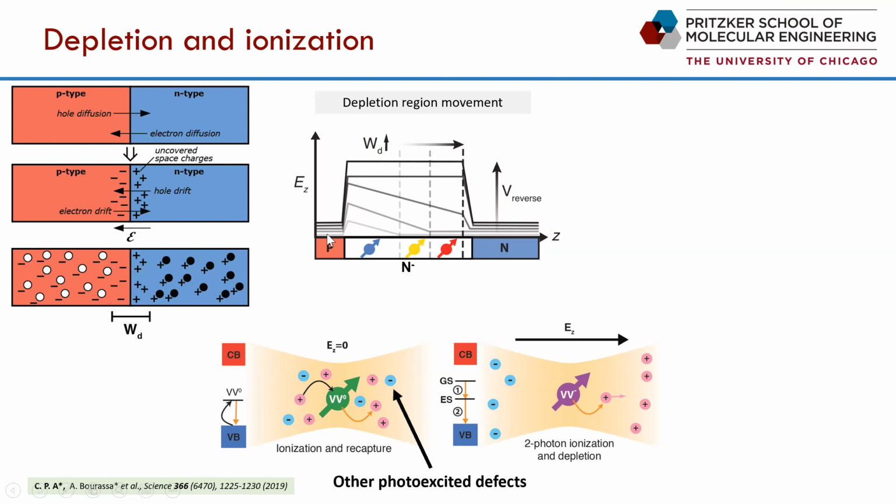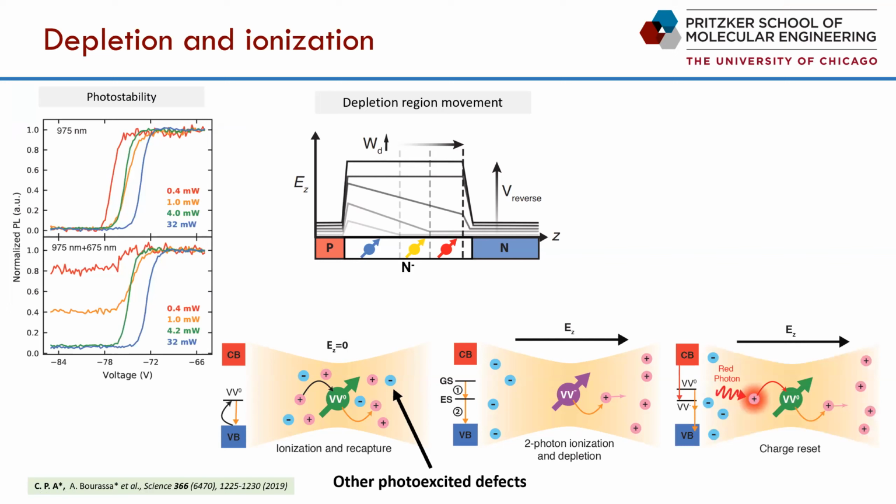Oh, I see. Okay, so it's just a function of the voltage that you apply. Yeah, exactly. We're applying more and more reverse bias, and the region's growing. Okay, yeah, gotcha. Thank you. Cool. Yeah, and this is the same physics that makes regular PN diodes work. So hopefully I convinced you that there's nothing fancy going on here. This is just traditional semiconductor electronics. Yeah, I had somehow mixed that in with the time scale, but those are two different things. Yeah, I think I kept saying time, but it's just increasing the reverse bias. Okay, got it. Thanks.